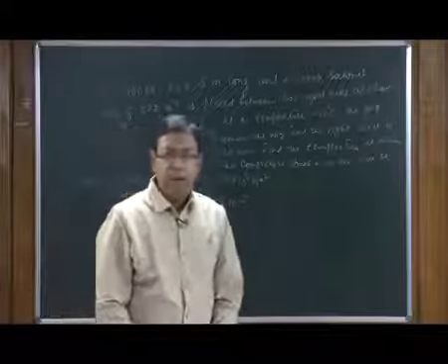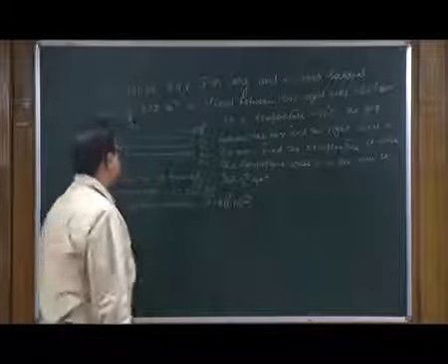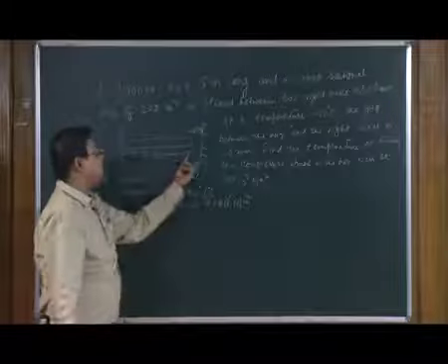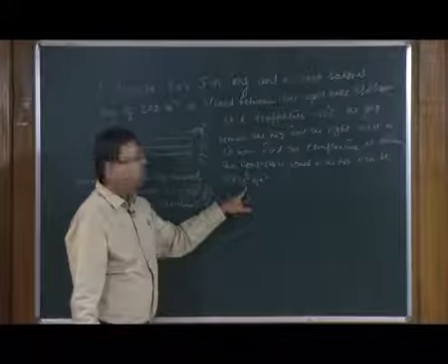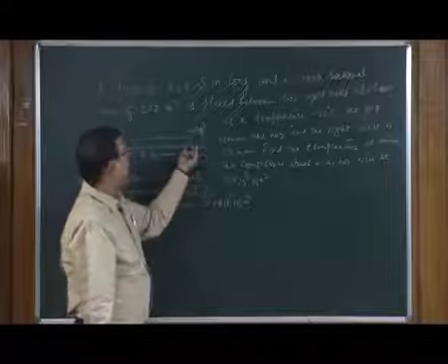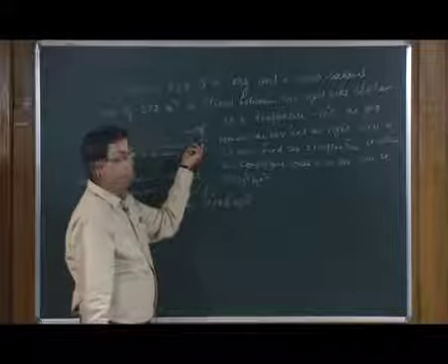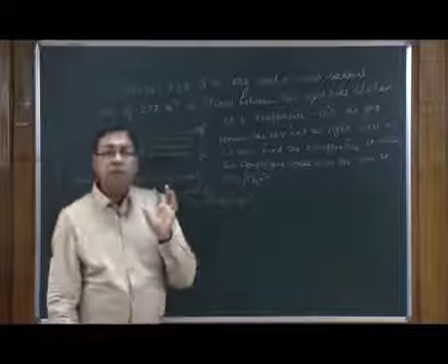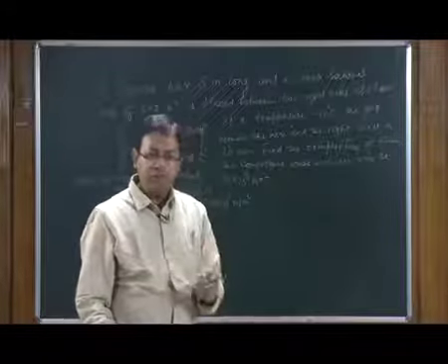You have to understand one thing in this problem, that the compressive stress of 30 into 10 cube Newton per meter square will come into the picture only when the rod grows by 20 millimeter and tries to expand beyond that because of thermal effects.